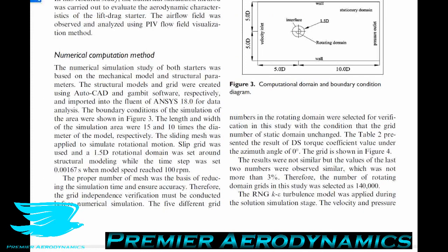You then take 2 quick pictures of the light sheet in very quick succession, so maybe separated by 0.1 microseconds or 1 microsecond or whatever you want. So in those pictures, you'll see the light that those particles have reflected. And if you look at the first picture and then the second picture, you can see where the particles have gone in that split second between the 2 pictures. Then you can determine each particle's velocity. So that's how we get particle image velocimetry.